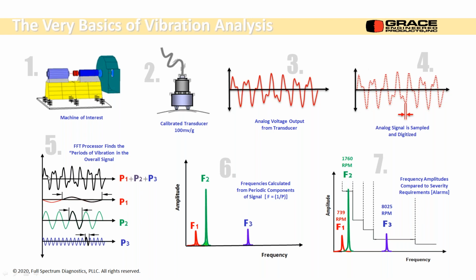So we have this complicated time waveform with lots of wiggles in it. Each one of those wiggles corresponds to something. If you overlay them all, they're all the periodic events inside that trace. The FFT processor finds the subtle low frequency period. It finds the more dominant second period in here, and then there's a third higher frequency period involved. Okay. Not real important how it does it specifically, but that's the easy thing.